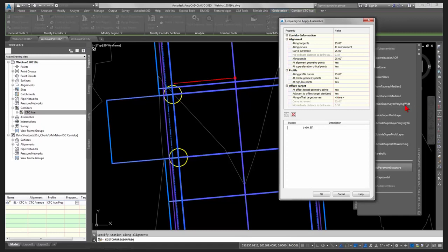Right now, because I had this set to yes and yes, it put another frequency line in 2/100ths outside. So that's why this came from here and then dropped straight down to the back. If I would have set this to no, it would have transitioned from this corner to this corner right here, because that was my next frequency line.